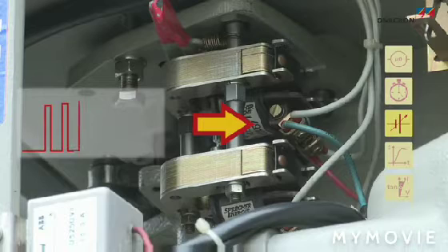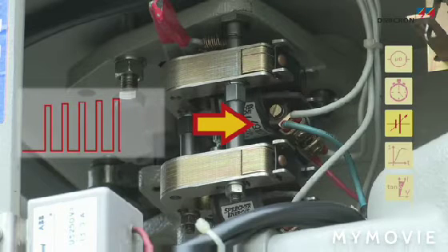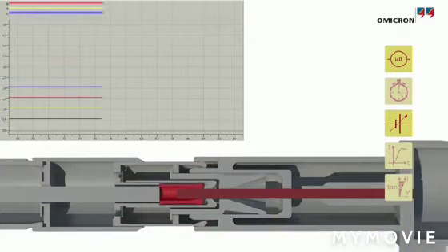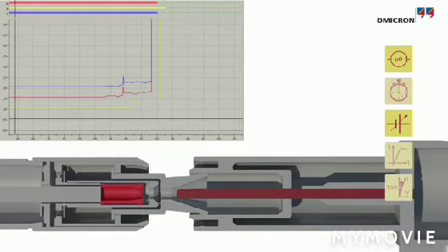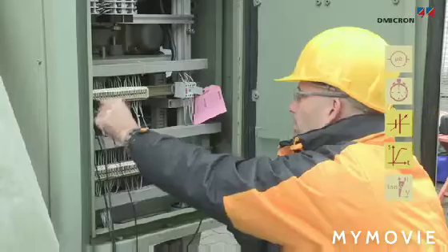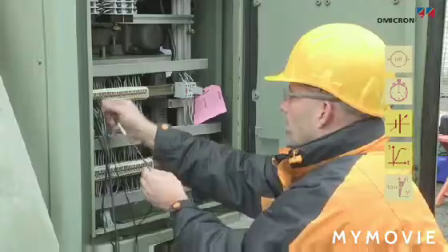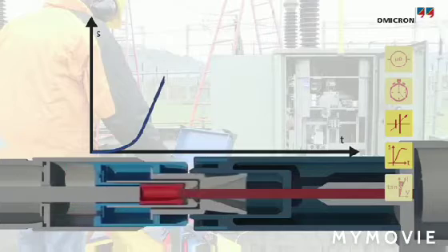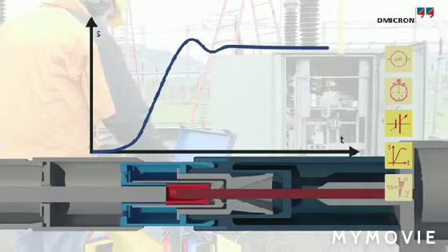The minimum voltage, known as minimum pickup, needed to trip and close the circuit breaker is also usually measured to ensure that it can still operate in case the DC supply is weak. If the breaker is equipped with a multiple contact system, measuring the dynamic resistance during opening and closing will indicate the wear of the arcing contact. Additionally, if the circuit breaker travel curve is recorded, it allows mechanical parameters to be assessed, such as velocity, total travel, acceleration, over travel, and rebound.